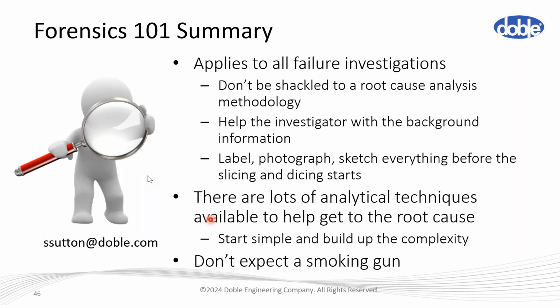So we have a question here about predictive methods and testing that we could use to know the health of our cables. That's an interesting one. It largely depends on the type of cable, whether it's an XLPE cable or an oil-filled cable. Oil-filled cables, people will do DGA sampling. The interpretation is difficult, and you need to make sure the samples are representative.